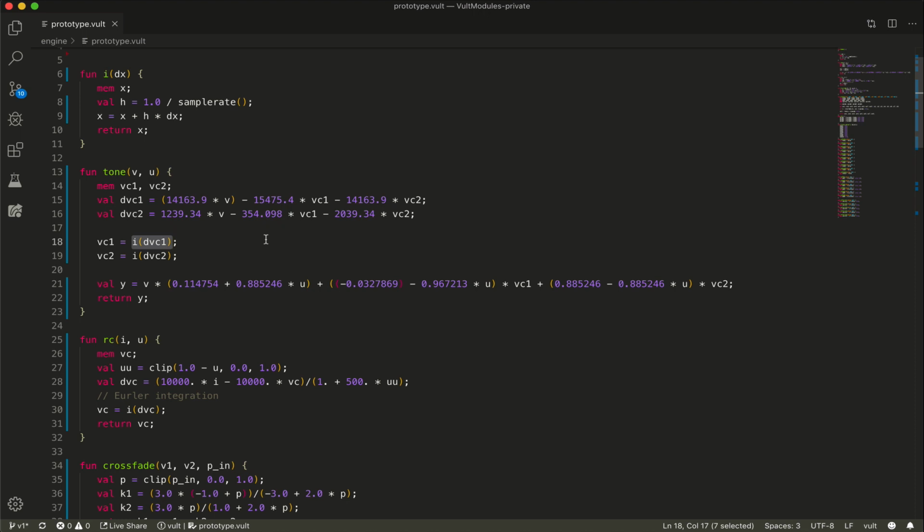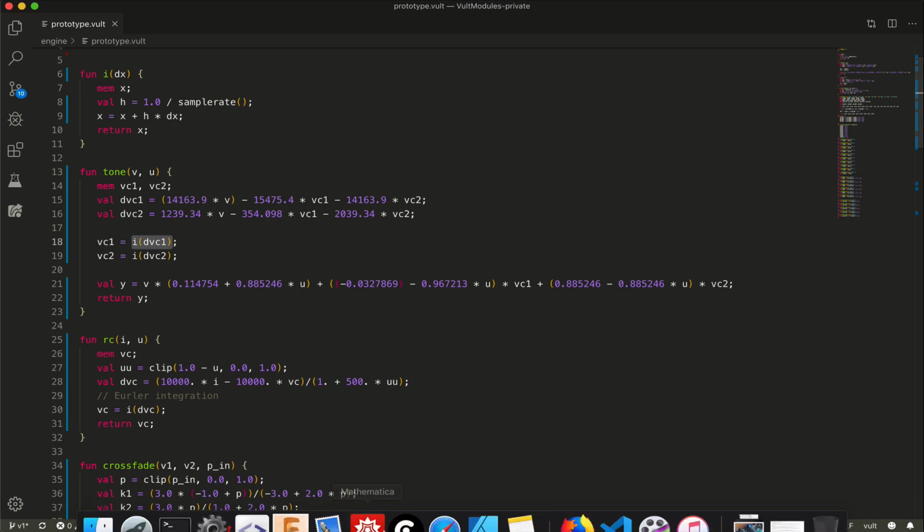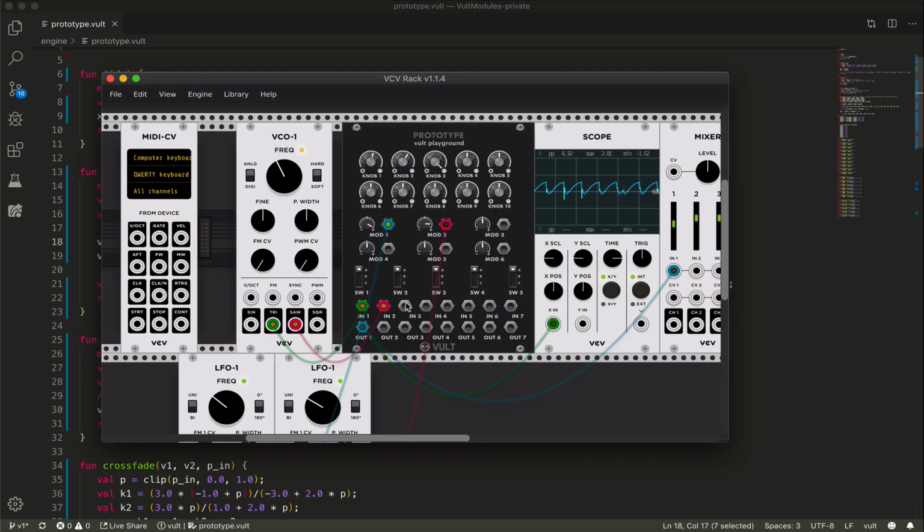So what you have to do in this case is make an evaluation of: do I really need that accuracy? Does it matter for this specific circuit? And if not, if your results are good enough as in this example, I would say that it's fine. There's no need of sacrificing more CPU.